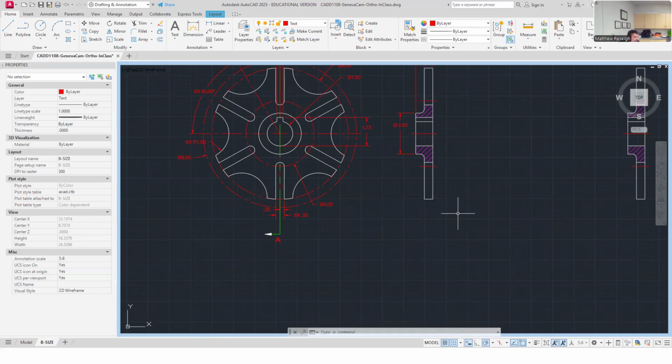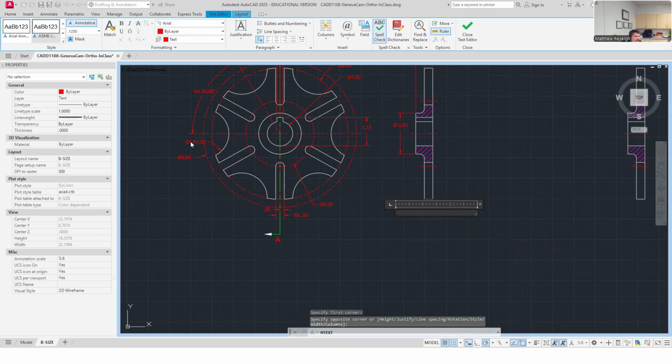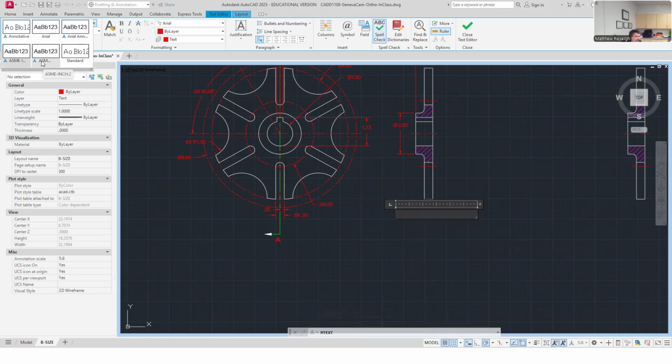Section views can be moved out of orthographic alignment. They can just be placed on the drawing where they need to go, kind of a removed section. So by titling it, it helps keep track of it. Mine's going to maintain an orthographic alignment, but I still would label it because it's not a normal right side view. It's actually kind of a special view. It's a section view, so we're going to name it. Section AA, and I'm going to do it with large font as well. My view labels are usually going to be large font, double the size. So this is section A-A, A through A.